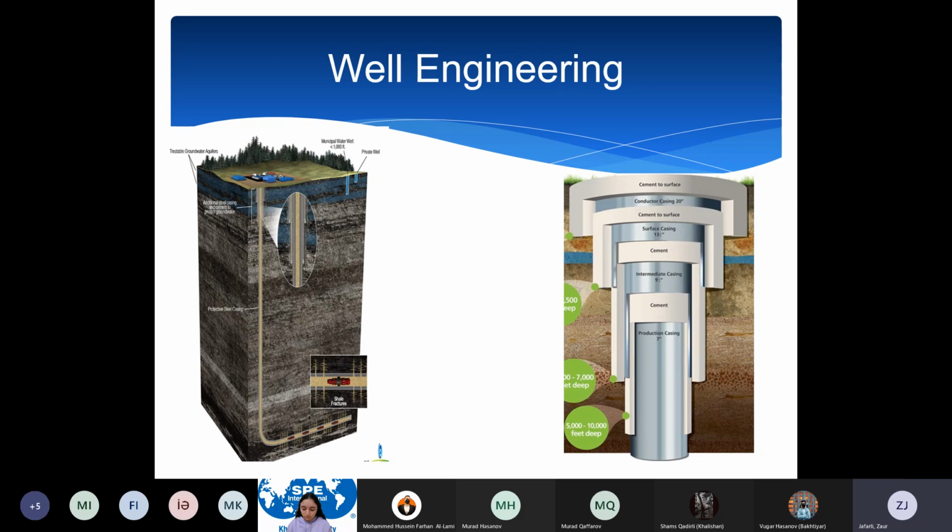Okay, what's going to be my tubulars to be run in that well, and then based on the tubulars, you need to design the production casing. Tubulars, I mean the completion string. It includes tubing, it includes different types of equipment as well. I'll talk to you about that in the next slides. And then, from the bottom up, you design your well and construct based on that.